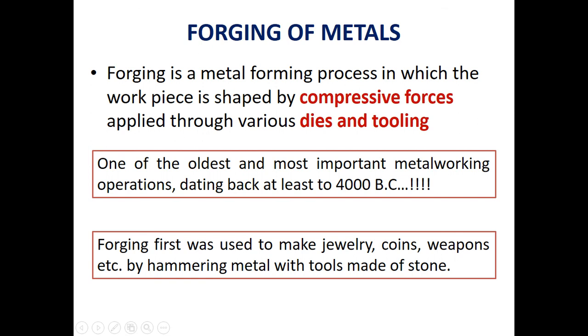As I told you, it is carried out in either hot or cold condition, but it's generally a hot working process. In this process the work material is heated and a force is applied either by impact or by applying a gradual loading to deform the material to the required shape and size.